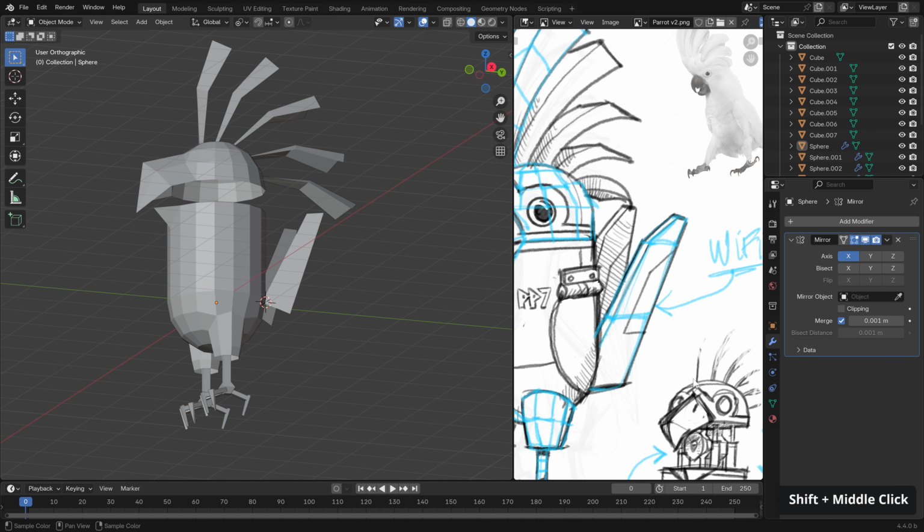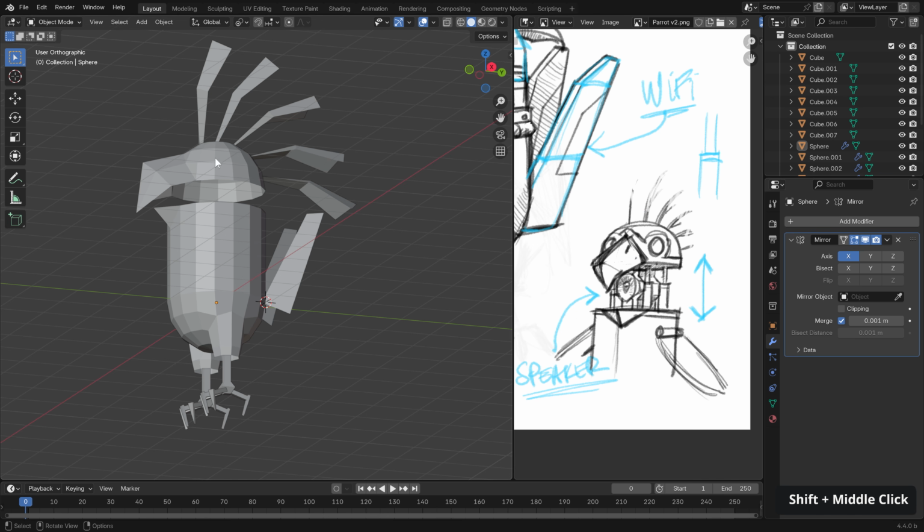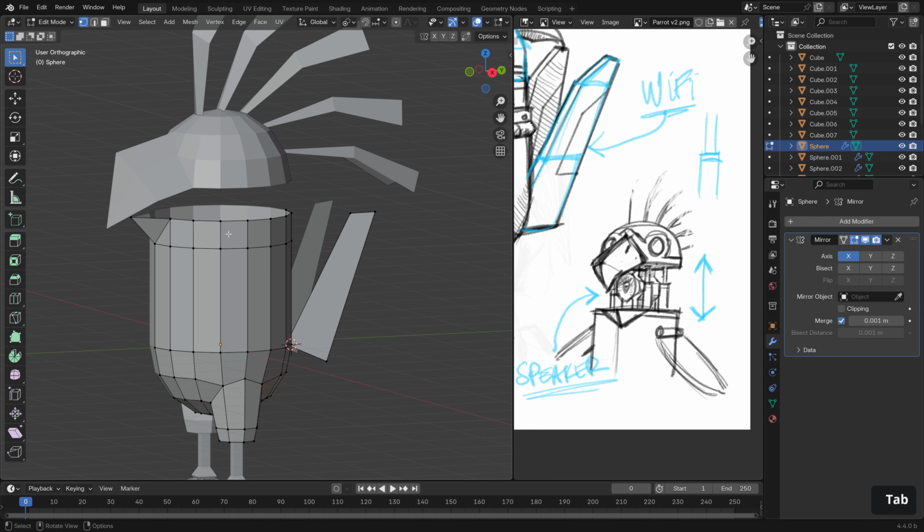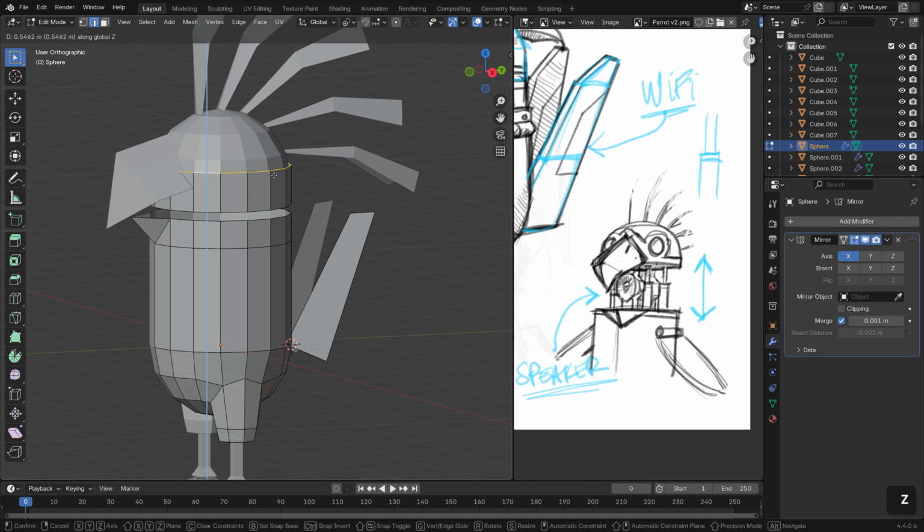And for the head here, we want to have this cool mechanic where the head opens up and reveals the inner workings. So we can use an existing circle of vertices. We've already manipulated this top row, but the one below it is all ready to go. So let's select in edge mode the semicircle here with Alt and left click, and then Shift and D and move it up like so. Then we can hit E and extrude it up like so. Just going to give it a little bit more.